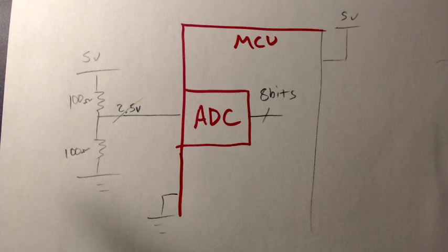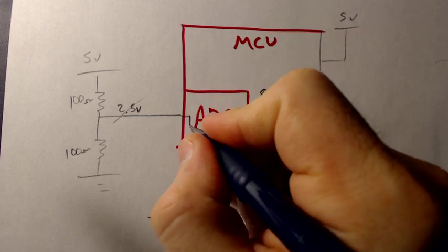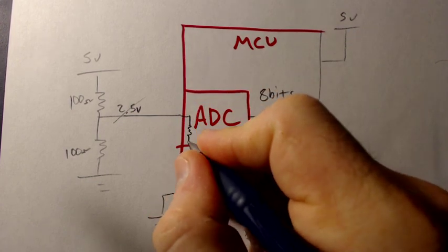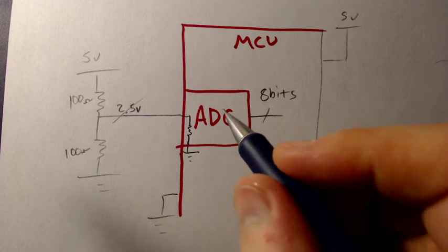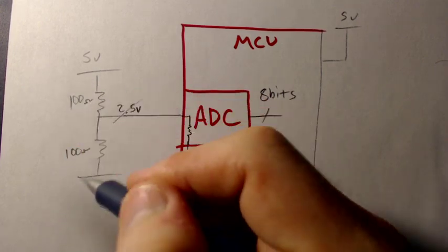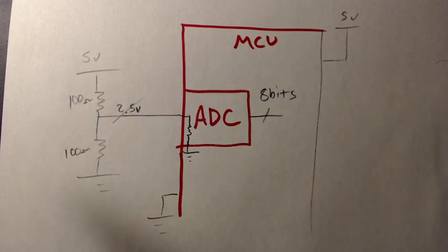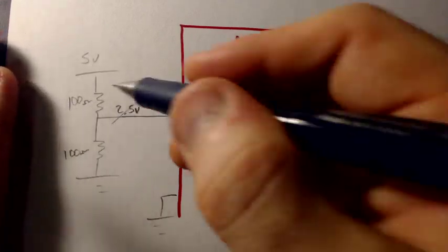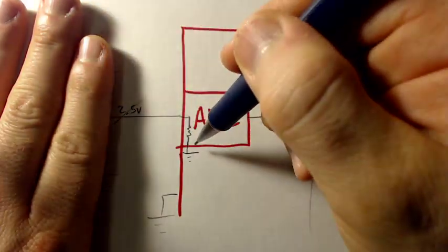It's not 2.5 volts because this analog digital converter has a little resistance over here, an impedance, and this has an output impedance, and this has an input impedance, and I just created a voltage divider between the voltage divider. I have two voltage dividers here, right? I have a voltage divider here, and I have a second one that's created between this and this.